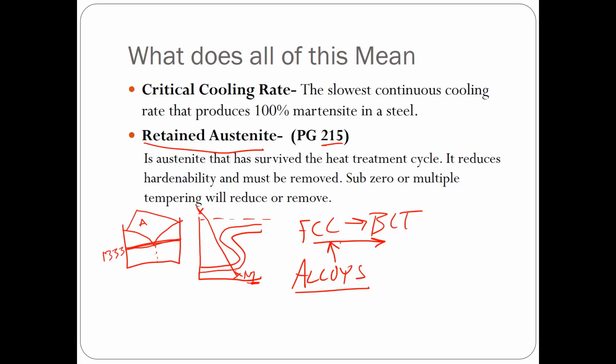So that's how it gives us way more time. Well, if the alloys are doing too good of a job, the FCC never kicks over and turns into body-centered tetragonal. So we end up with retained austenite. Why doesn't it kick over once it gets down at lower temperatures?